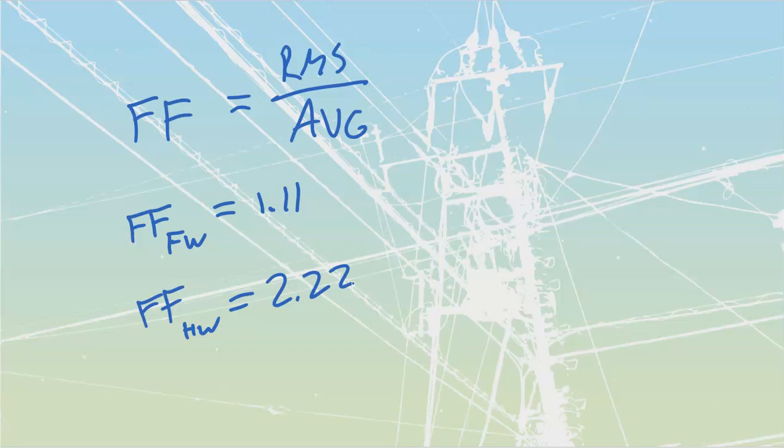What we use form factor for is when we know that we have a circuit and we have a rectifier and we want to know values from one side over to the other side. Here's the first example. They're going to say we've got a single phase bridge rectifier. What is that? That's going to be full wave that we would be talking about. So we've got a bridge rectifier. Say that's a BR over there. And they're saying, look, we're going to use a bridge rectifier because we need full wave DC.